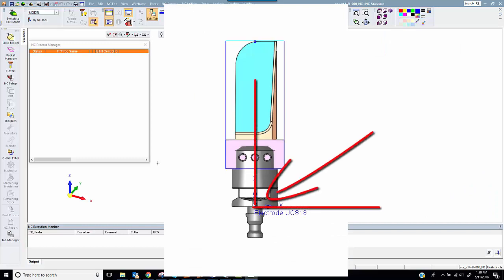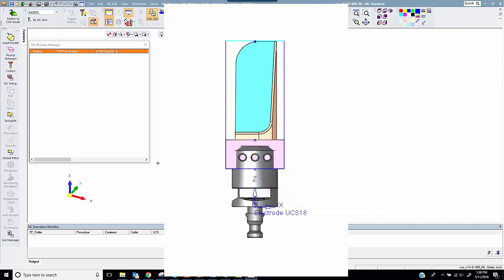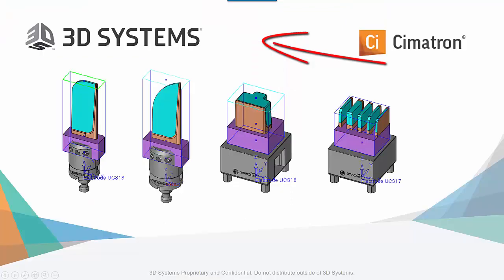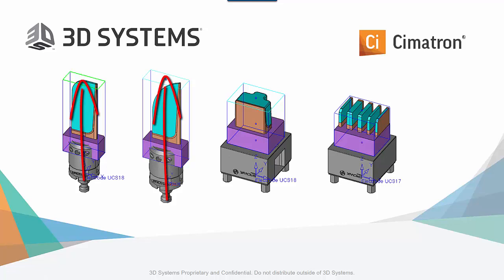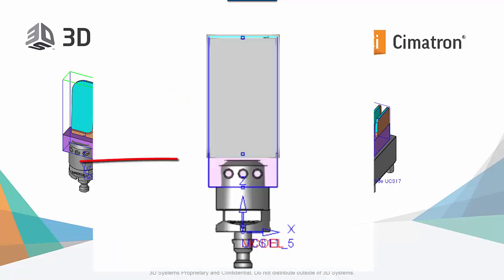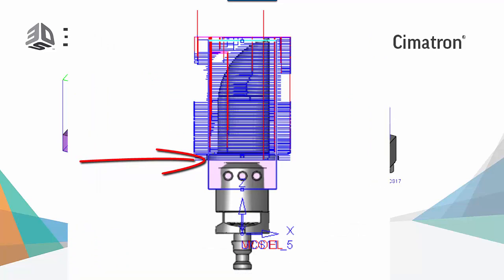Many shops today set their Z origin at the bottom of the electrode holder. This reduces burn depth errors when compared to working from the tip of the electrode. The biggest issue with this is that the height of the electrodes is variable and the height of the holder is variable. It makes it a little harder to grab a standard template that will not overfinish and will not hit the base. There are a couple ways to handle this. All roughing procedures stop at the bottom of stock. If the stock stops just below the top of the base, then the roughing will too.